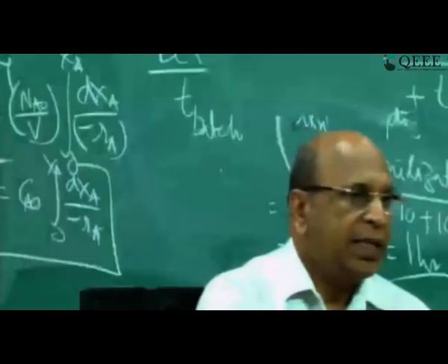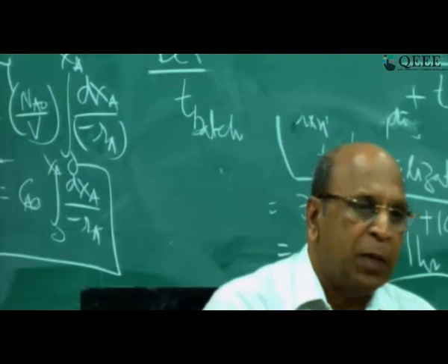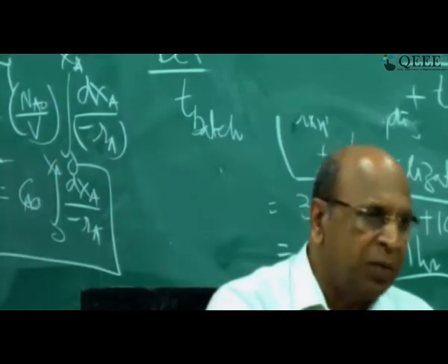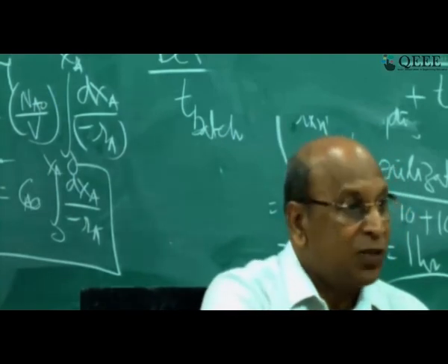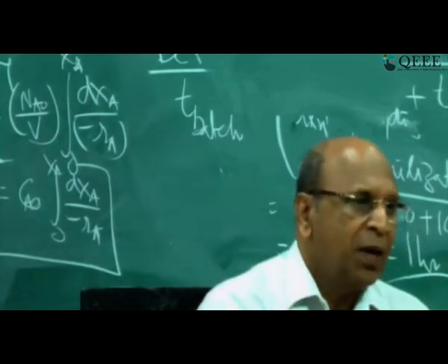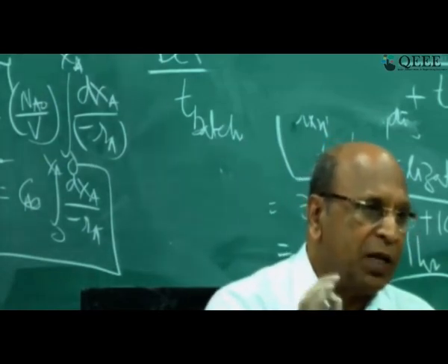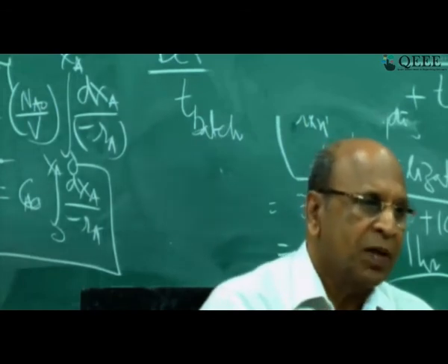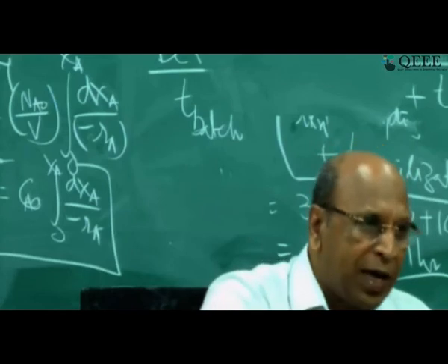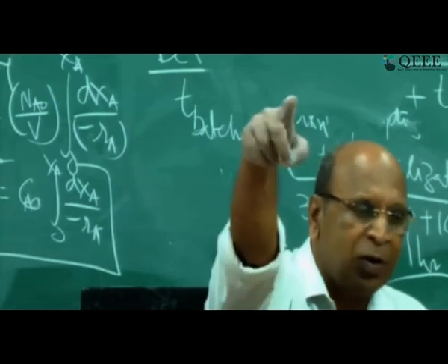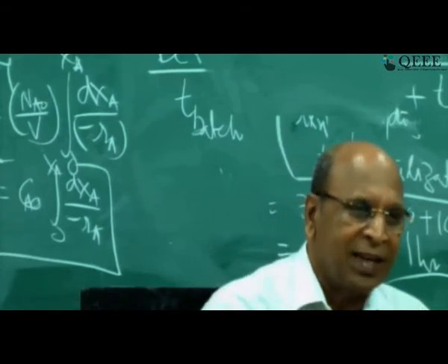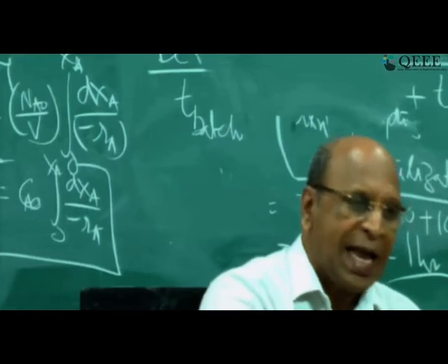Okay? Is it possible to carry out biochemical reactions in a PFR? Yes, because the microorganisms are so small, right? Theoretically, PFR can be used, but the problem is biochemical reactions are very slow reactions, right? So theoretically plug flow can be used, but you should have a length of maybe 100 kilometers of plug flow reactor. That is why it is easy to use tank reactors.